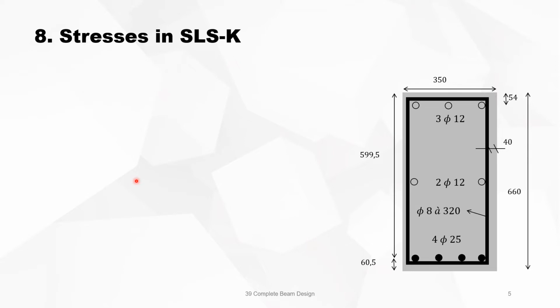First, have a look at the stresses in SLSK. In SLS it's only checking. There is no design that we will do in SLS. So this is the section as it is now. The bending moment in SLSK was 291 kilonewton meter.